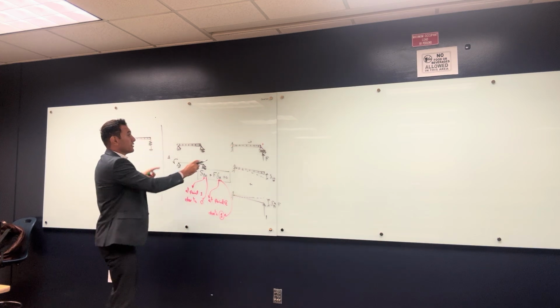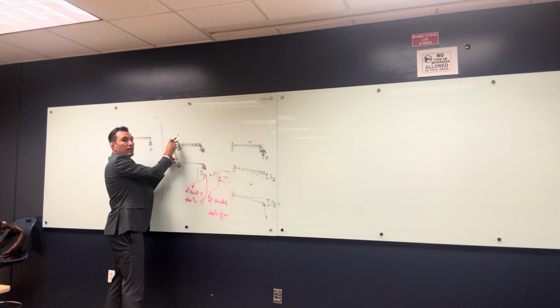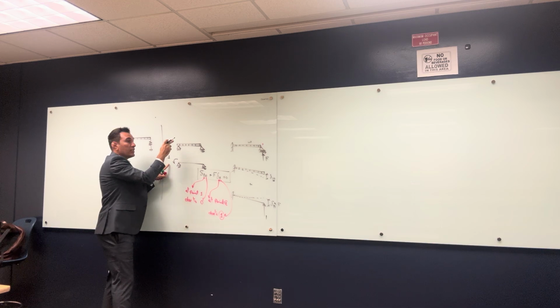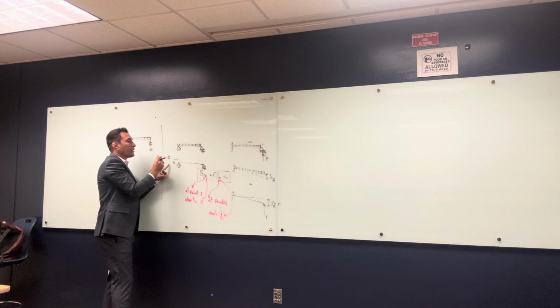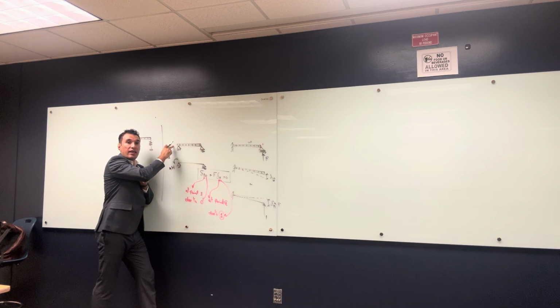But when I release the moment here and make this system, here this theta is not gonna be 0, right? So I need a force, a moment that can counter this theta to make it 0. So I assumed it 1, but actually it's gonna be at the end m multiplied by 1, and I wanna find the value of m. So I wanna find the value of the moment that is gonna bring the theta here to 0.